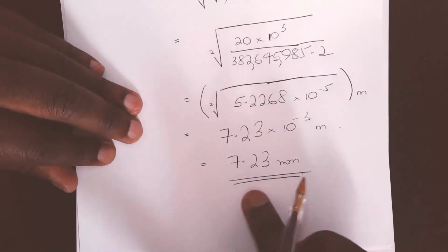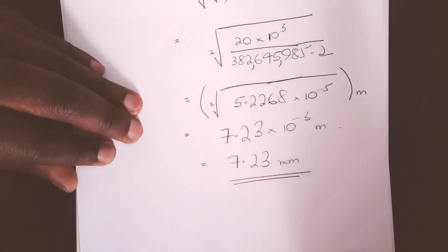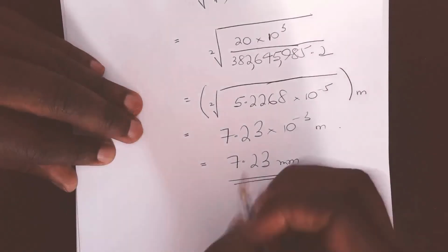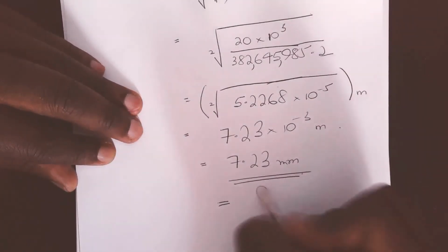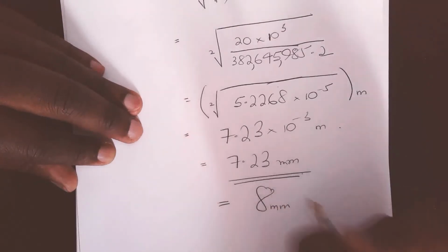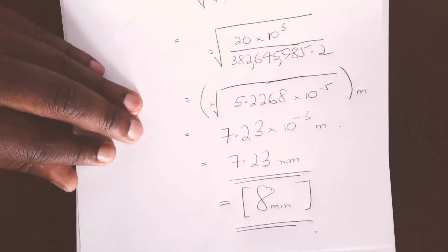It doesn't really make sense machining or fabricating a fastener to that diameter, it's just a waste of money. It's best to get what's already in stock or what's already standardized. So, the best standardized bolt size to get will be 8 millimeters. If 7.5 is available, then that's fine, but I think it's best just to round up to 8 millimeters. And there we have it.